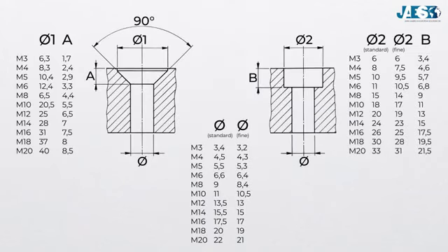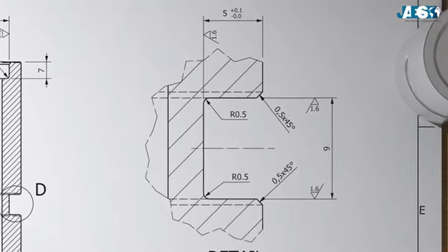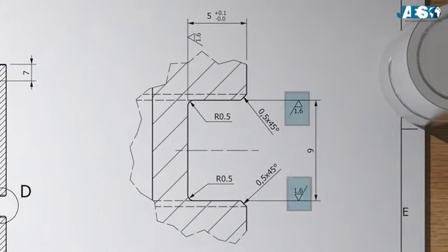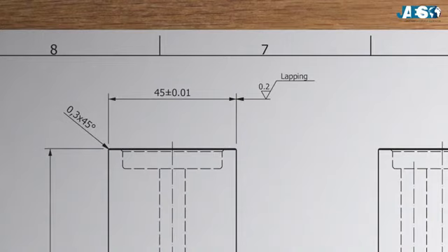Often, the hole has a countersink or a counterbore that serves to accommodate the head of the screw, which is specified with dimensionings and is standard according to the type of screw. Along with the dimensions, one can also indicate the surface roughness index of that particular face, which may deviate from the general roughness index. Finally, there may be notes for machining processes or warnings.